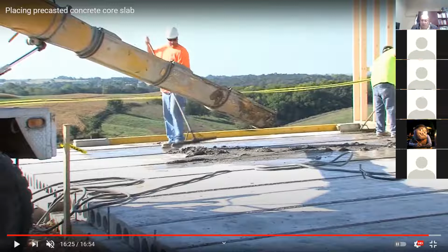When we pour the concrete, most likely it is going to be a PT slab. So when the soil shrinks back again, the slab itself is able to take the loads from the top. And if pressure comes from the soil, the slab is also able to take the pressure coming from the bottom. This is the reason we like to use PT slabs. It's going to be much stronger.